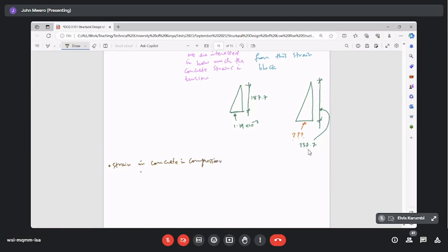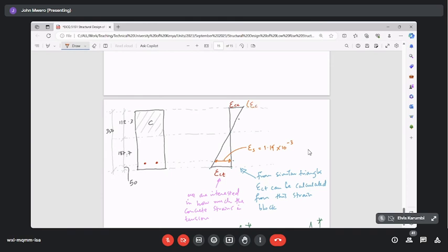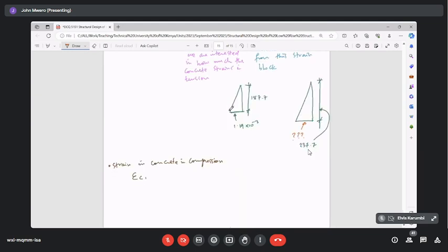We've said we really don't need this for crack calculation, but some standards call this EC1, and those standards also, if they use numbers, call the other EC2. So that's what I'm referring to here. EC1 will be, you'll check these numbers later, just a simple calculation of those similar triangles, 10 to the minus 4 in compression. Then strain in concrete in tension.